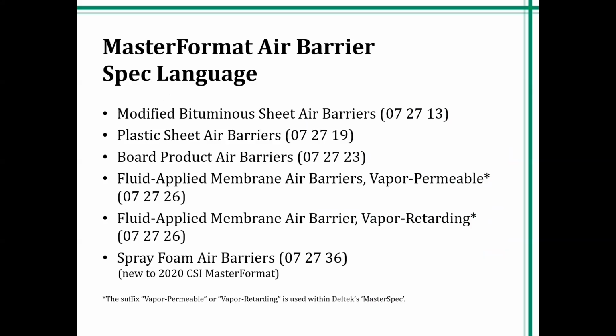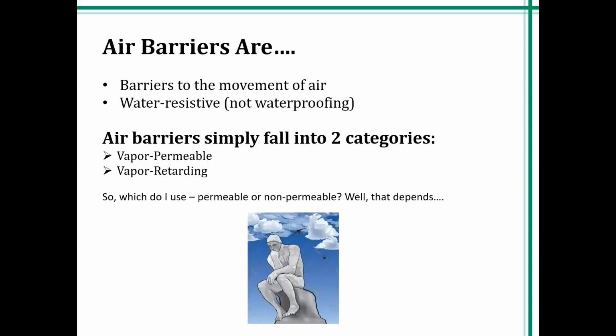And frankly, I tend to like it because when I'm reviewing a spec and I see that title, I know exactly what it is. If I see something that says weather barriers, for example, which I really abhor, I don't really care for that because you have to drill down into part 2, hopefully, to see what the physical properties are that we're specifying. So an interesting heads up. Anyway, air barriers are just that. They are what we should be calling them. They're not air and vapor barriers. They're not moisture barriers. All air barriers are inherently water resistant.